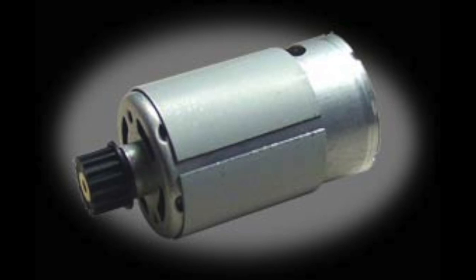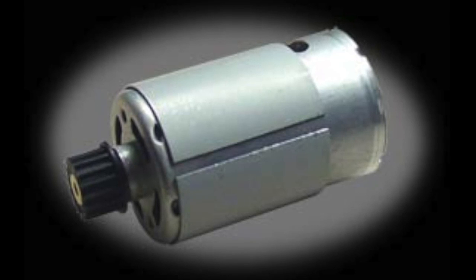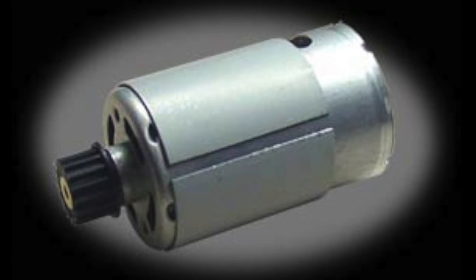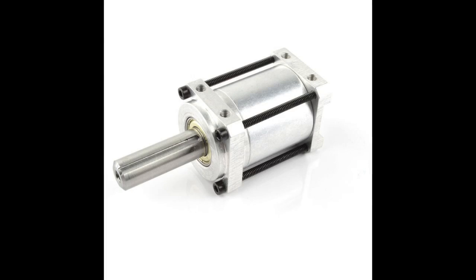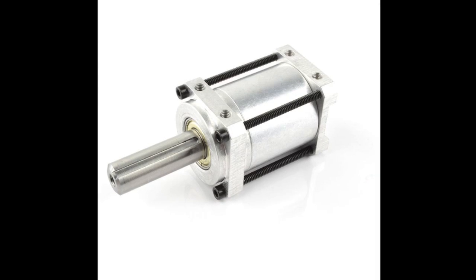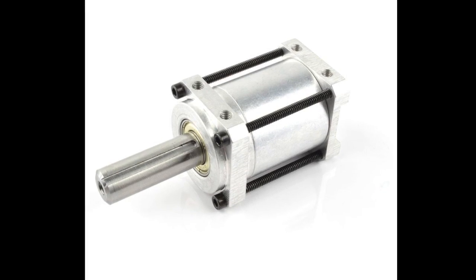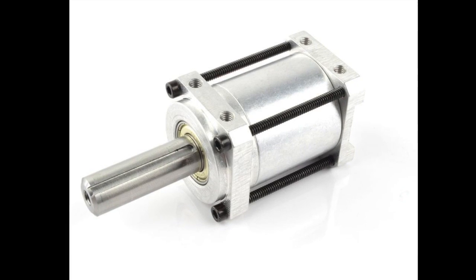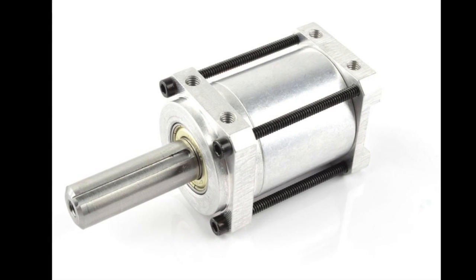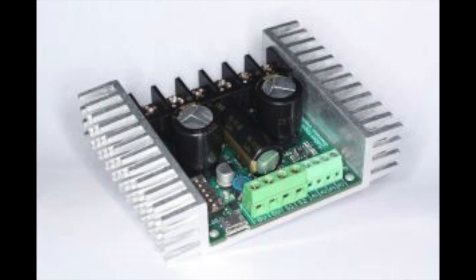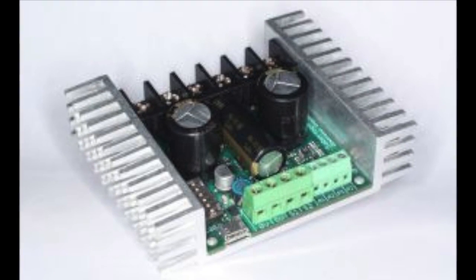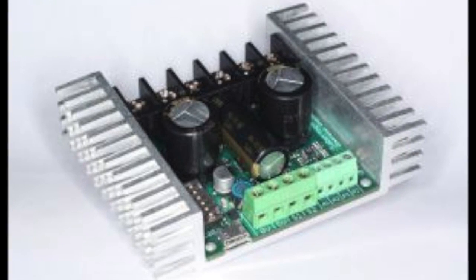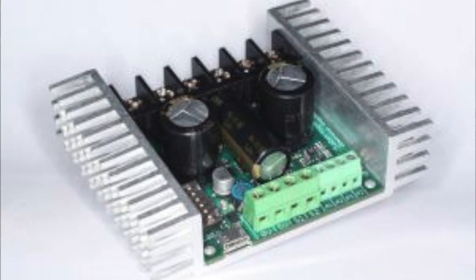We used two RS550 motors. These are 12-volt DC motors with a maximum torque output of 0.488 Newton meters. For each of these motors, we used a Bain-Botz P60 gearbox with a 64:1 gear ratio in order to achieve enough torque for balancing a person. To control the motors, we use a dual 2x32 amp motor driver. This motor driver controls both motors using simple serial communication protocol.